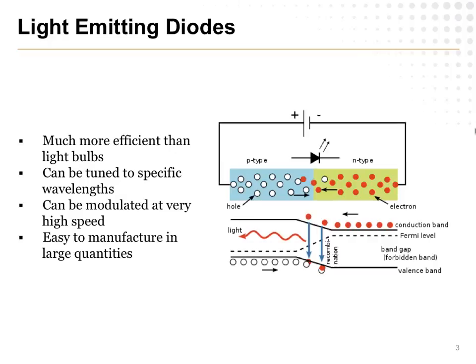A lot of the LEDs we worked on when I was doing the infrared LEDs, a 1 to 2 microsecond rise time was easy, and that was without even really trying to make them fast. So right out of the gate, they're at the megabits per second kind of threshold, just by the simple virtue that you can turn them on and off very quickly, so I can send lots and lots of bits per second.